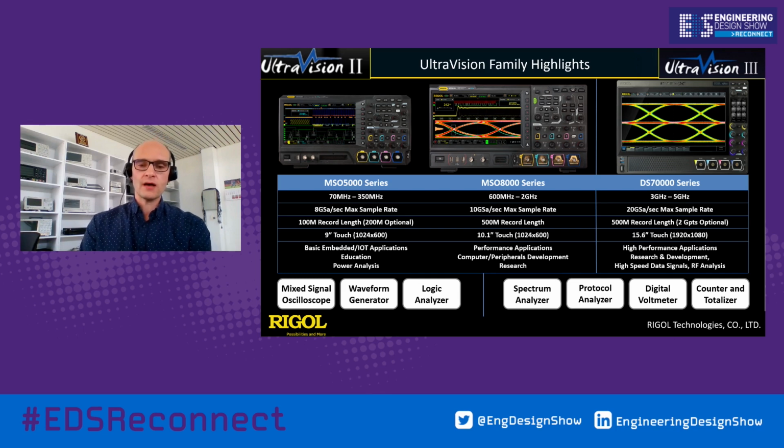Both scopes are multifunctional oscilloscopes, which contain a mixed signal oscilloscope. That means 16 digital channels and 4 analog channels. The MSO5000 is, for example, an 8 gigasample oscilloscope, and the MSO8000 is a 10 gigasample oscilloscope, which also has the capability of spectrum analysis with FFT functionalities, with protocol analyzer, and with a waveform generator.